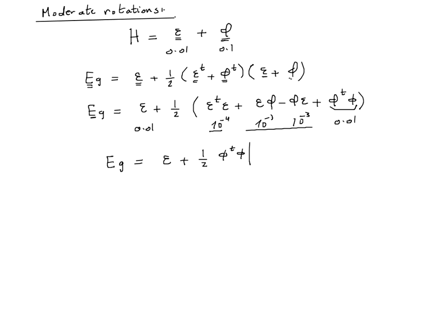And this is going to be the basic equation we use whenever we go for nonlinear theory. So all our buckling predictions and our derivation for buckling equations, stability equations, will be based on this equation here that says that Green strain can be approximated as the small displacement strain, which is linear in displacement, and then quadratic terms, but they are not a linear function of the strains, they are a function only of the rigid rotation.